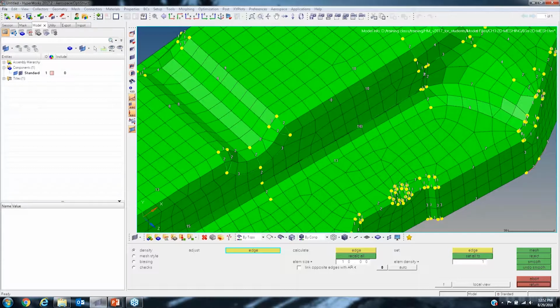So normally, a lot of people try to minimize the number of triangular elements that they have. There are some things you can do to be able to get better results using triangular elements. But for the most part, you don't want to use triangular elements very often. There are some cases where you would have to, like if the geometry is very complicated, you'll have to use all triangular elements. But in some cases, you'll have mostly quad elements. And what you'll find is, depending on the industry and the area that you're working with, some people, like for example aerospace companies, tend to only want quad elements.